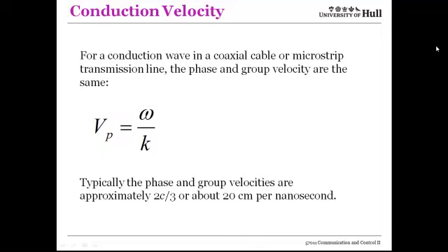Now, for the signals and conduction paths that we're dealing with, a signal will typically propagate at about half to 2/3 of the speed of light in free space. Now, the speed of light in free space is about a foot a nanosecond, so typically our signals will propagate about 20 centimeters in 1 nanosecond. So for instance, your laptops and computers will have clocks that are going through several cycles per nanosecond, and during a single cycle a signal will only propagate a short distance across your computer, about the distance from the Q key to the T key, for instance.